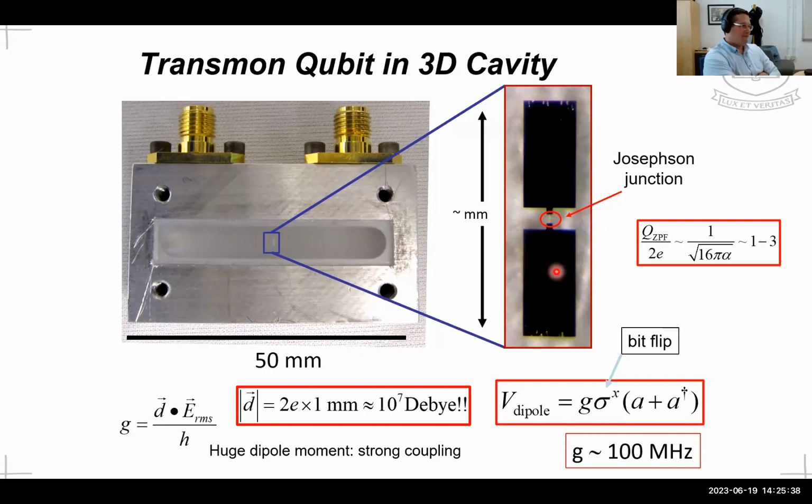In the cavity, well, okay, now it's not a lumped element picture. This is, by the way, about 1/10 of a wavelength at the resonance frequency of the qubit. So that's why you can get away with a kind of lumped element approximation. The wavelength's much bigger than the object. Here, the wavelength is determined just by the size of the resonator. So it's not a lumped element thing. It's a continuum.